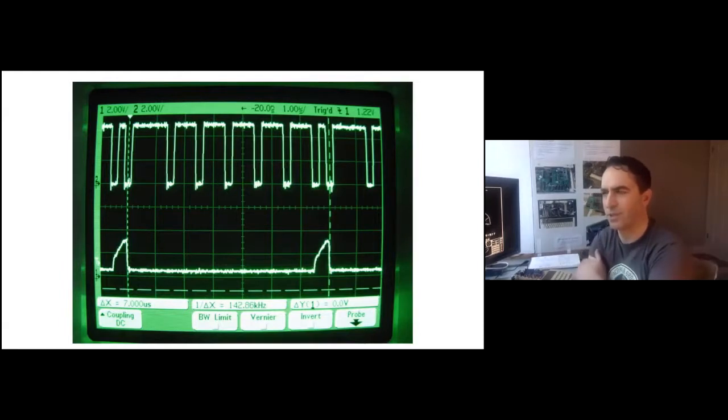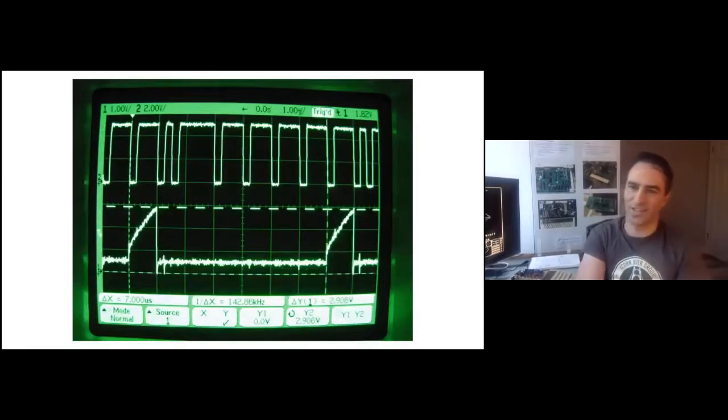It turned out this was because of some synchronization that I'd added, because we had an asynchronous address signal coming straight into a block RAM, which really felt like the sort of thing that you shouldn't do in an FPGA. So I'd put some synchronization in, but it also resulted in the ULA code getting the address a cycle too late and stretching the wrong cycle for the keyboard. Fixing that, ta-da, keyboard works well. Now the keyboard lines get up to 5 volts before the falling clock edge, and so yeah, it's reading properly.